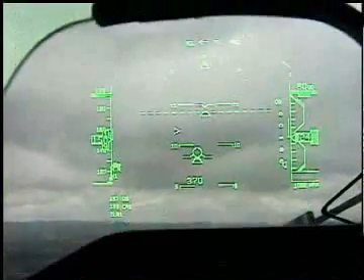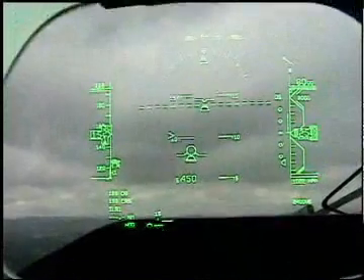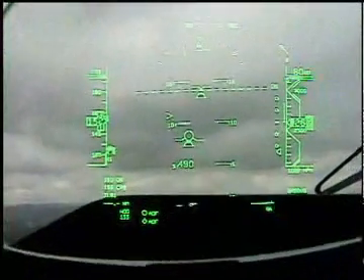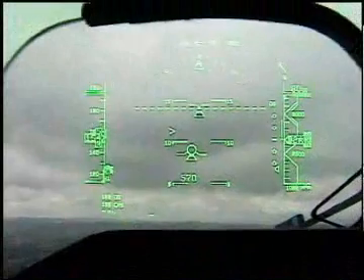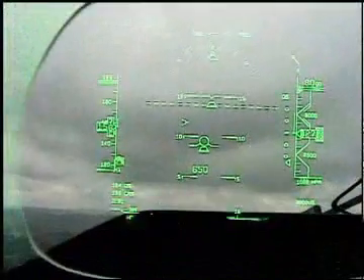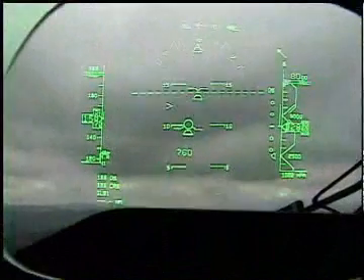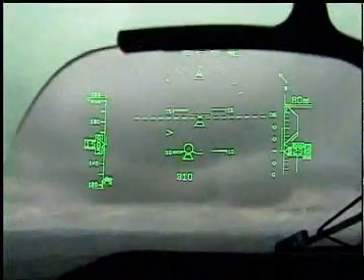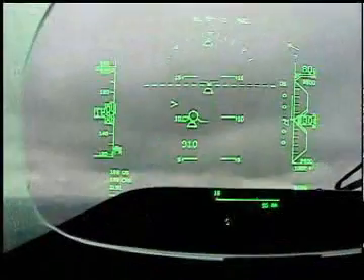In the event of an engine failure, the speed error tape, referenced to V2, will be displayed. Flight path acceleration symbol is useful in determining a positive climb gradient and optimizing climb performance. When the desired pitch attitude and airspeed is achieved, placing the flight path acceleration at the wing of the flight path symbol will maintain the optimal initial climb performance.